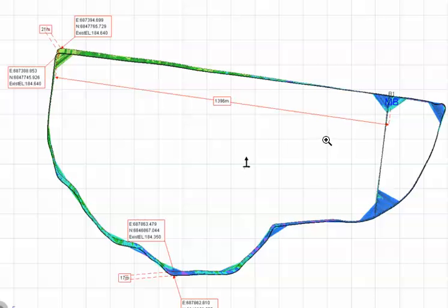And the other thing is, depending on how large your slopes are. If your slopes range from, say, just for argument's sake, a steep slope that's 10%, and then at this point, at 20 meters, say there's 20 meters out and it's sloping 10%, then you are going to be 10% of 20 meters, which is 2 meters. You're going to be actually 2 meters out in the vertical with vertical error. So you can see that's going to be a massive amount of error.